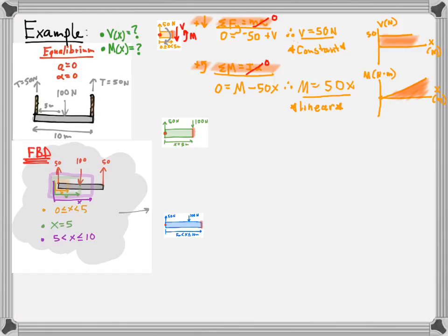So we're running out of time here. We're going to continue on with the next section, but I want to show you what we're going to do next. We're going to evaluate the green volume, and we're going to evaluate the blue free body diagram, and we're going to produce an in-depth analysis of what's happening inside the structure. So far we've seen that our shear force will be constant, but our moment will be increasing the further out we go, because this shear force is going to have a bigger and bigger moment arm the further out we go.